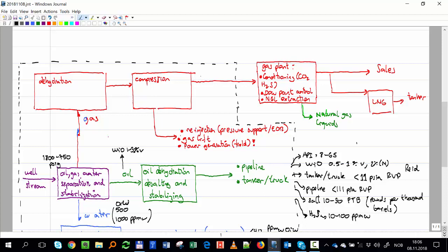And yeah, so this is usually called, I have the name here, rich gas or wet gas, rich gas pipeline. Okay, and rich because I haven't taken yet any of these heavier hydrocarbon components. The pressure that we normally use depends a bit on the place, but it can go between 80 and all the way to 200 bar. Okay, we went back to SI.